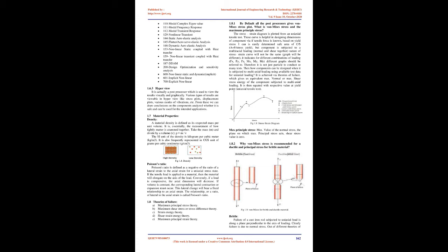A few of the most common solution sequence codes are 101 linear static, 103 modal or dynamic, 105 buckling, 106 nonlinear static, 107 direct complex eigenvalue, 108 direct frequency response, 109 direct transient response, 110 modal complex eigenvalue, 111 modal frequency response, 112 modal transient response, 129 nonlinear transient, 144 static aeroelastic analysis, 145 flutter/aeroservoelastic analysis, 146 dynamic aeroelastic analysis, 153 nonlinear